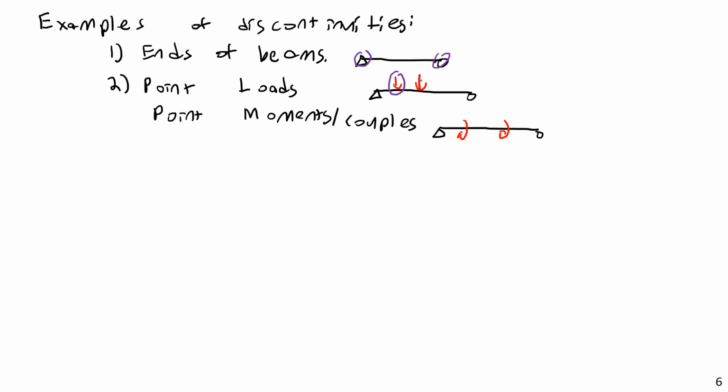Point loads, those represent discontinuities in beams. And couples also represent discontinuities in beams. Now, couples are not going to cause discontinuities in the shear function, but they are going to cause discontinuities in the moment function.